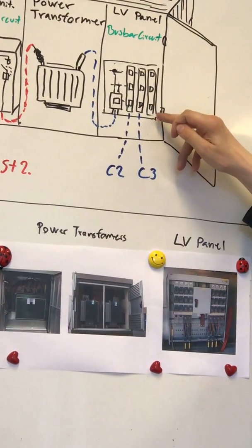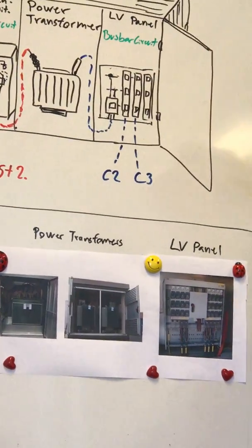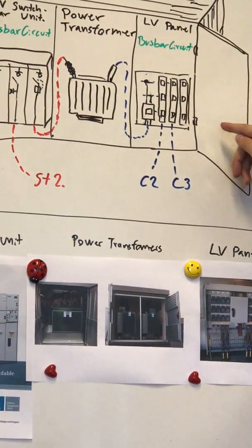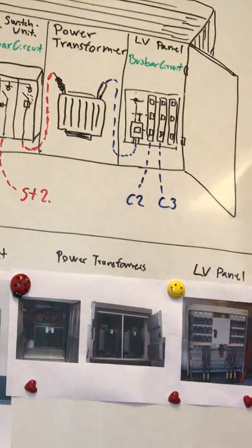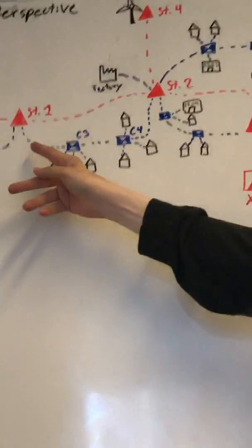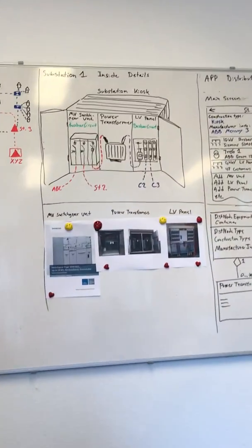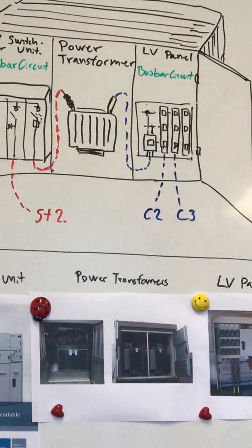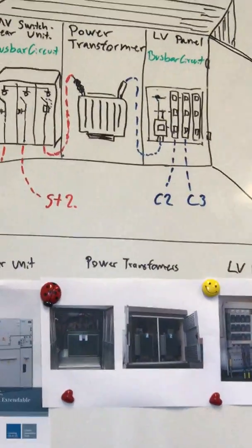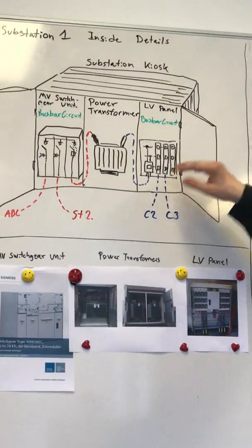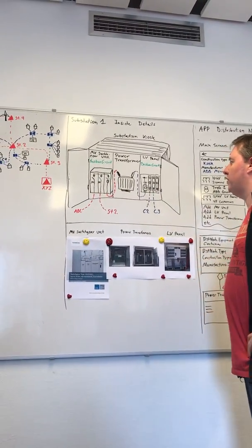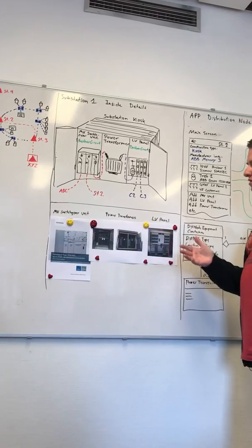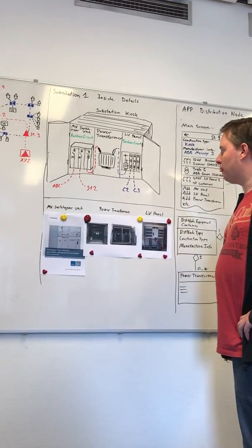But just to show that there can be spare ones, it's important for the technician to register when he uses the app and sees, okay, it has this, this, and this. Okay, it also has some spare ones. We have to register them too, because the next time they have to connect, maybe they have to build a new area here. They have to connect a new cable box, because sometimes someone just builds some new houses and then they need more power. So we have the spare one, and they don't need to come and put a new one in. Then they can connect later. So that's why it's important that they can register also the one that's not connected yet, because then they can see in the system, okay, there's a spare one here. Because today many systems don't have this registered yet.